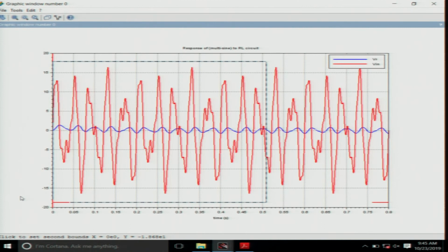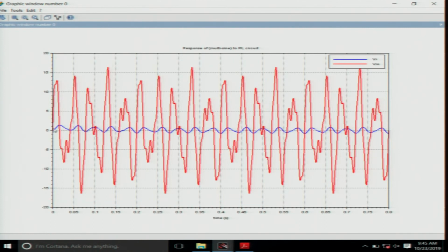Remember that right in the beginning there is of course a natural transient. Okay. So this natural transient is there as we can expect it to be. You can notice that there is a slight DC offset initially in the blue waveform and that decays. So you still have this e raised to minus R by L t right in the beginning when you switch on this circuit. That is an interesting point which you should always remember, that you do have a natural transient, it dies down and eventually the output wave shape has the same frequency components as the input.